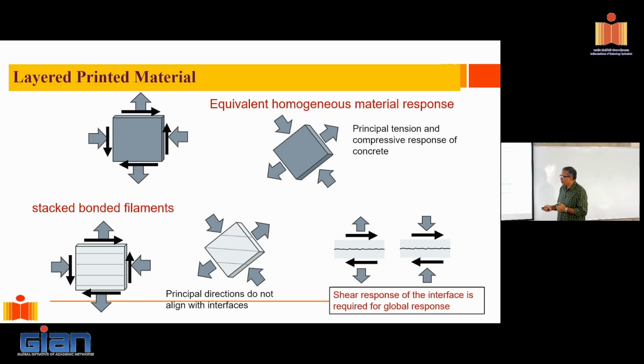Because of the anisotropy, what happens is that because of this structure here, I end up with a stress state on the interface, which will always have some tension and shear or compression and shear. That's the problem with the masonry structures. That's exactly where I'm headed, actually. So that's exactly what happens.